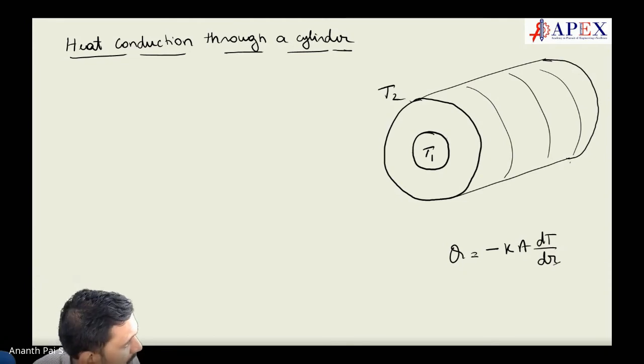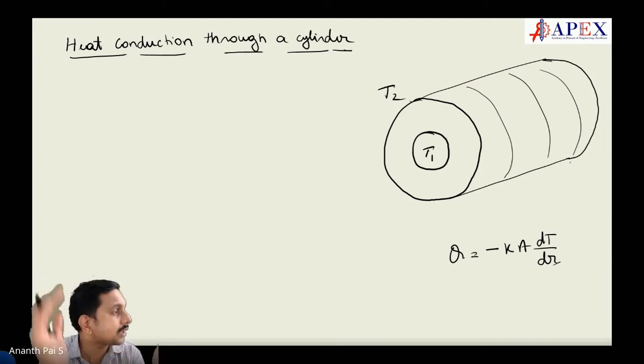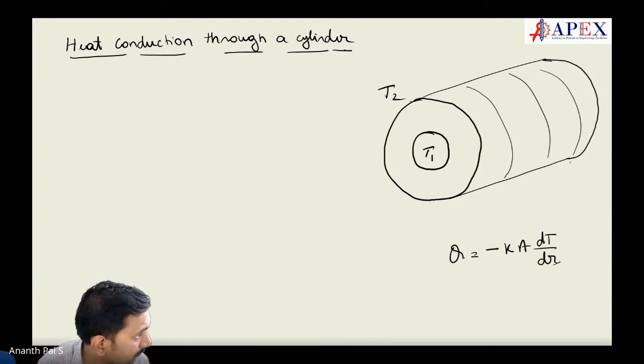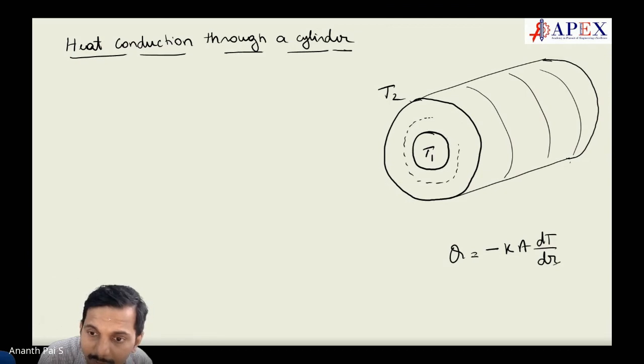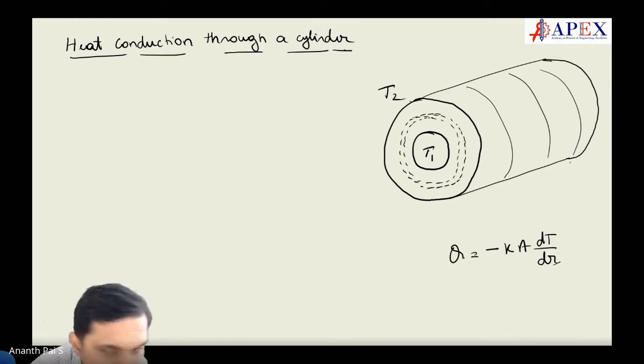This is the area. Initially, the heat transfer is like this. The area is perpendicular to that. That area you have to take. So what we will take? So here integration helps. So let us take a small, infinitesimally small strip here, where the area variation is less. So let us take from the center at a distance r of a radius, thickness of dr.